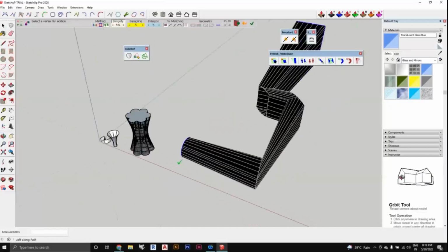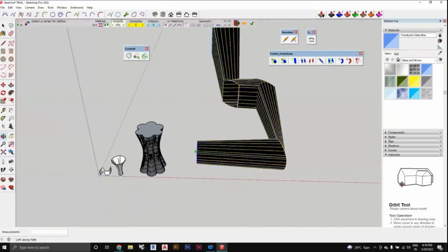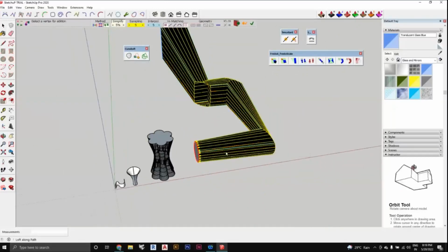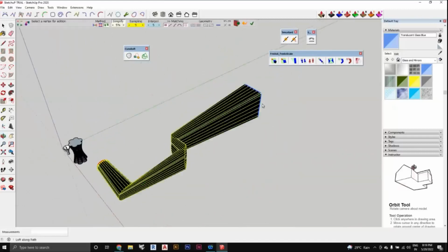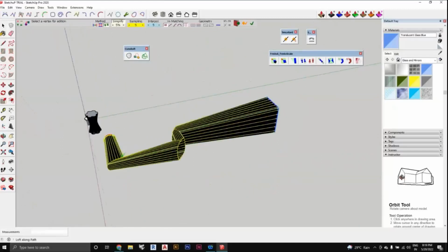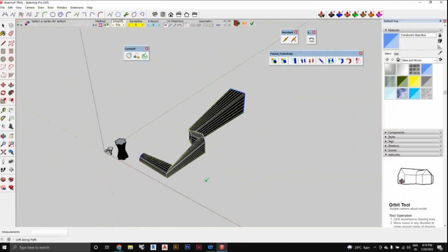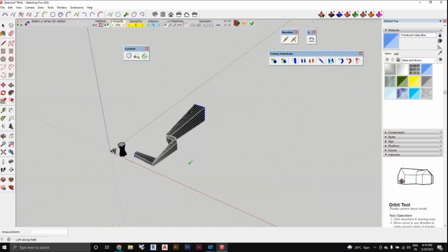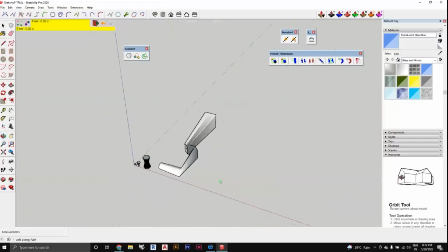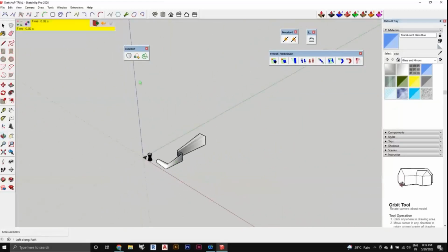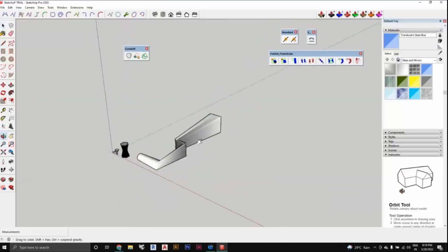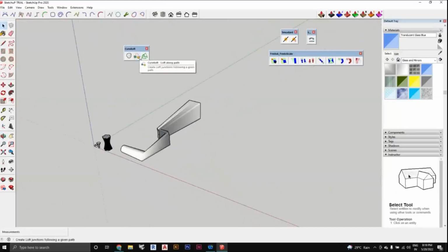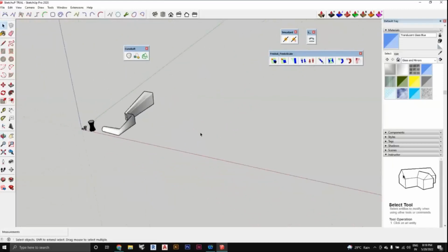So now what you can see is that from this point it will be a circle, and then it will start trying to become a rectangle as it moves along. So that is what this tool does to your shape. If you press once more you will escape out. And that is the function of loft along path. So any doubts?